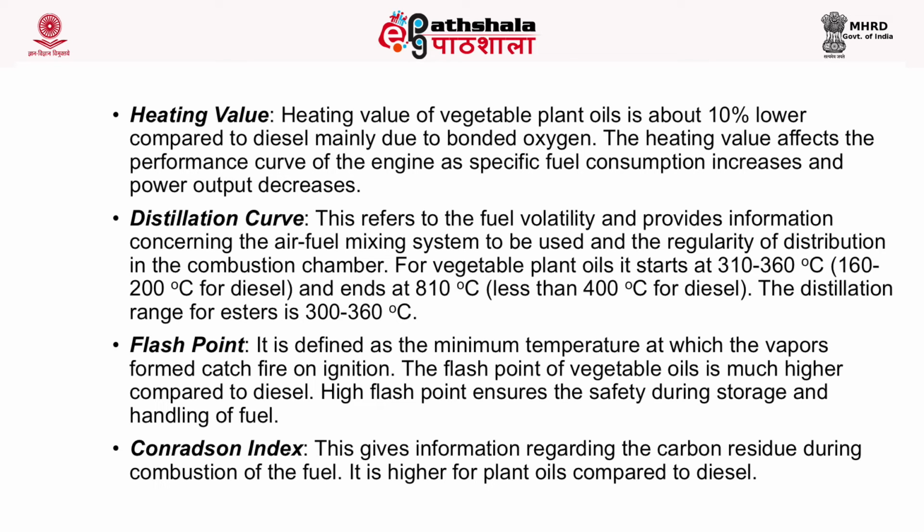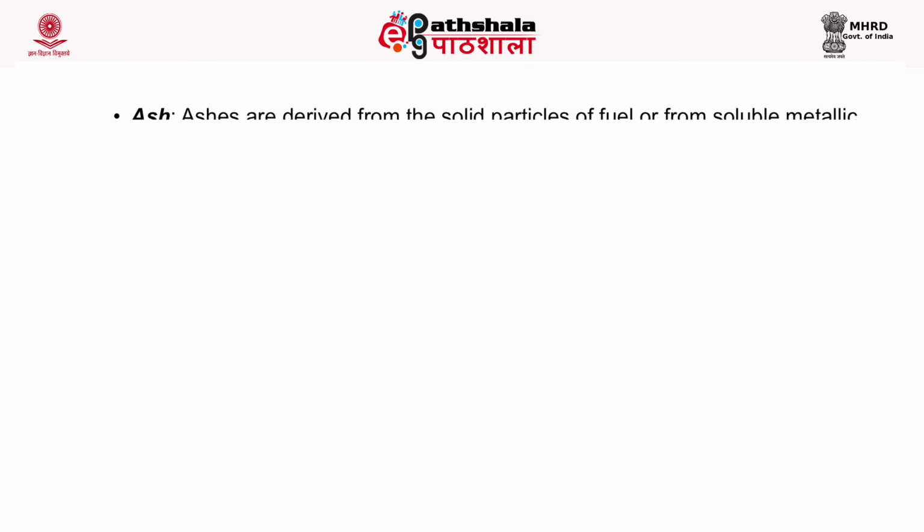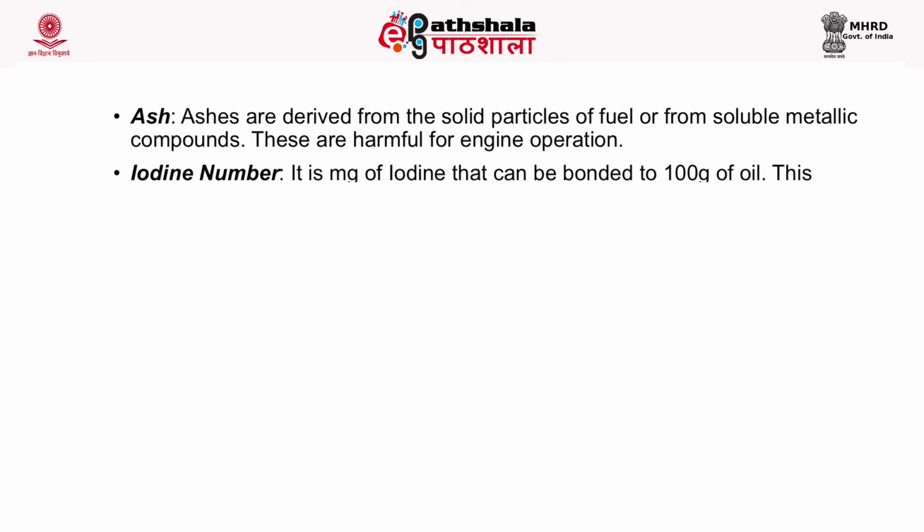Next is the condensation index. This gives information regarding the carbon residue during combustion of the fuel. It is higher for plant oil as compared to diesel. Next is the ash content. Ashes are derived from the solid particles of fuel or from soluble metallic compounds. These are harmful for engine operations.